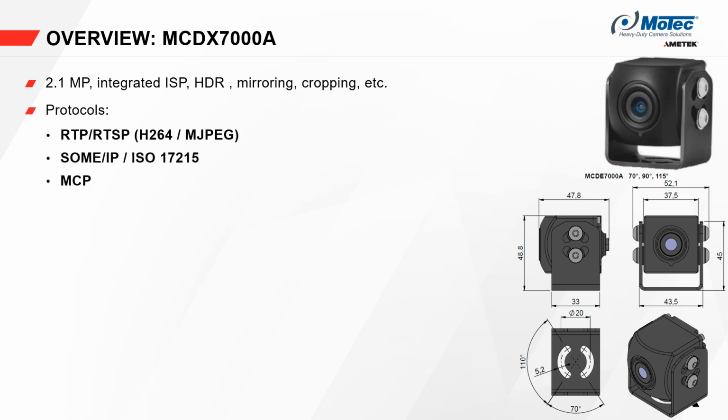The camera supports RTP and RTSP for video streaming, allowing you to seamlessly integrate it into the most common streaming applications. You can toggle between the H.264 and Motion JPEG codec, allowing you to adjust the camera to your specific application. When it comes to configuration, it supports the SUM-IP protocol, also known as ISO 17215, as well as our own Motec control protocol. The Motec control protocol allows you to change any parameter of the camera easily with a very simple to implement interface.